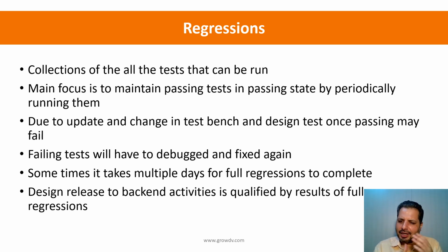And after fixing, again you need to rerun those set of tests to make sure that the full test suite is passing. And then you break up this test suite into different sets of test suites to manage different configurations, or you could be taking a subset of tests and performing low power simulations on those.